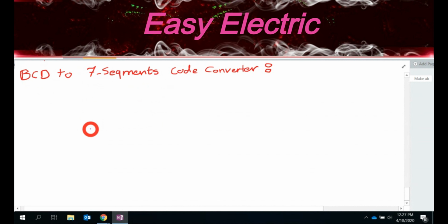So I actually make one table which summarizes what I want to do. On one side, what should be the input for this unit is the BCD codes, right? Remember chapter 1, the BCD code is a 4-bit code, which is the binary of that digit, right?